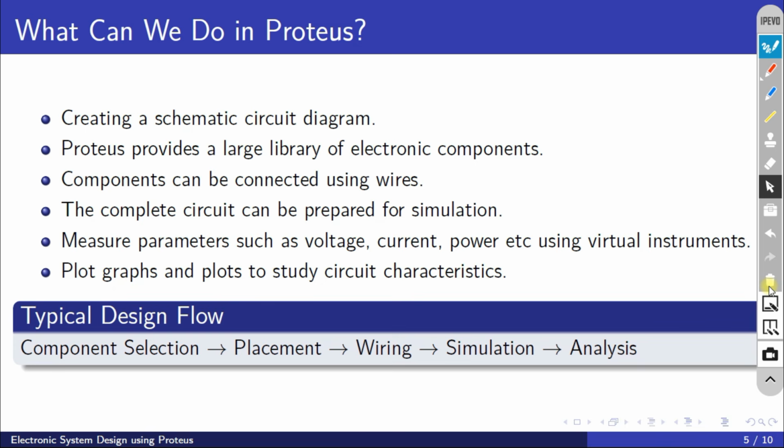Once the circuit is completed, we can run it using the simulation feature of Proteus. During simulation, we can observe the behavior of different components and signals in the circuit. We can also measure parameters such as voltage, current, power, etc. using virtual measuring instruments provided by Proteus.